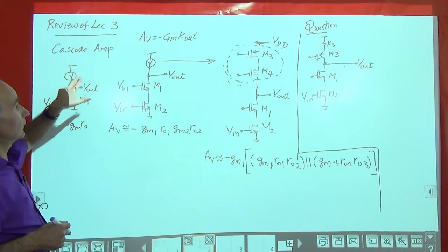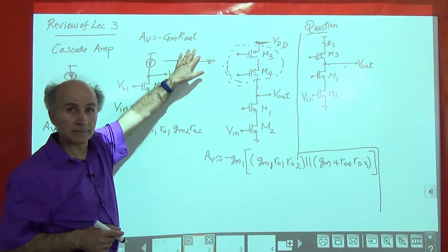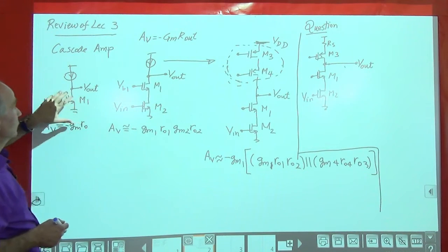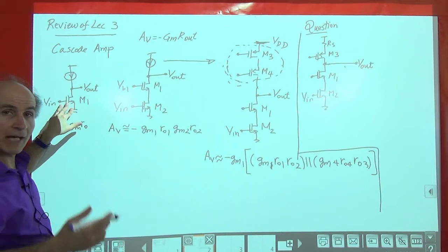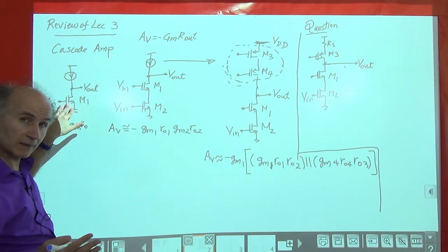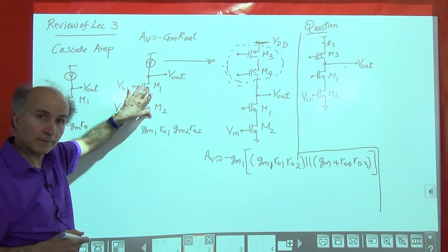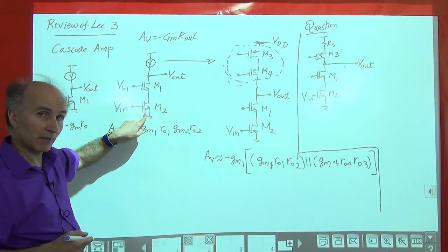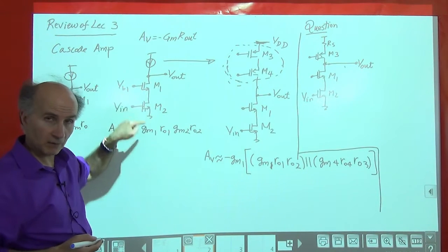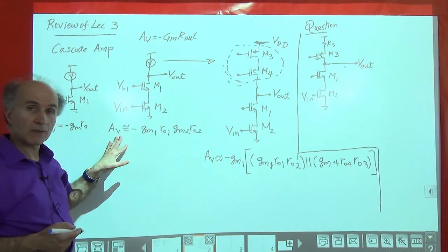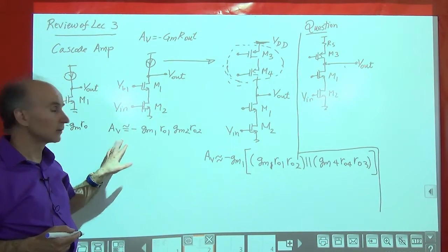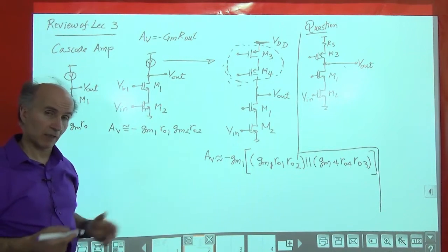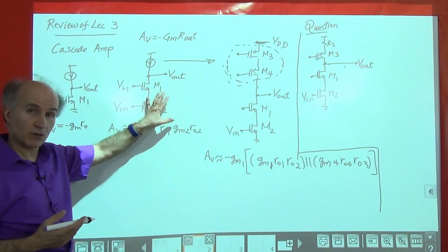And then we said, okay, to increase the voltage gain, I can either increase gm or Rout. And it turns out that increasing gm is not that easy. But increasing Rout is a lot easier. So we decided to think of a topology that has a higher output resistance and perhaps the same amount of transconductance. And we came up with the cascode amplifier. We saw that the transconductance of the overall circuit is approximately the same as that of the input device, but the output resistance is higher, because we have a cascode structure. And after some simplifications, we saw that the voltage gain of the circuit is approximately equal to the product of two intrinsic gains. So maybe 100, maybe several hundred, depending on how much these values are. So that's encouraging. It says that we can increase the voltage gain of the circuit.